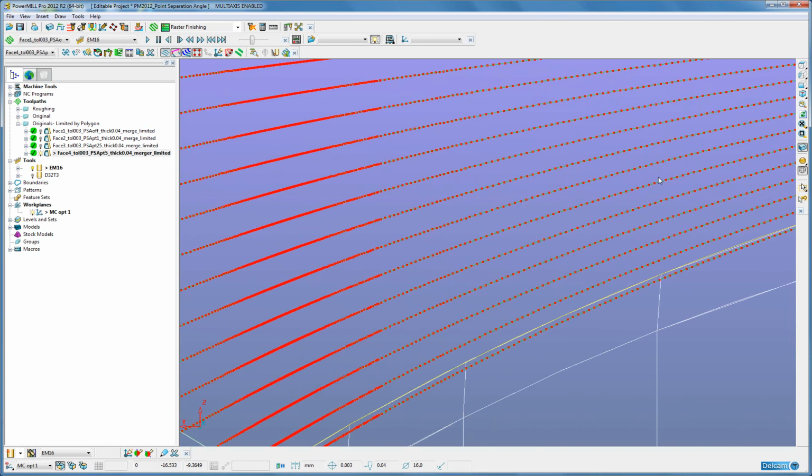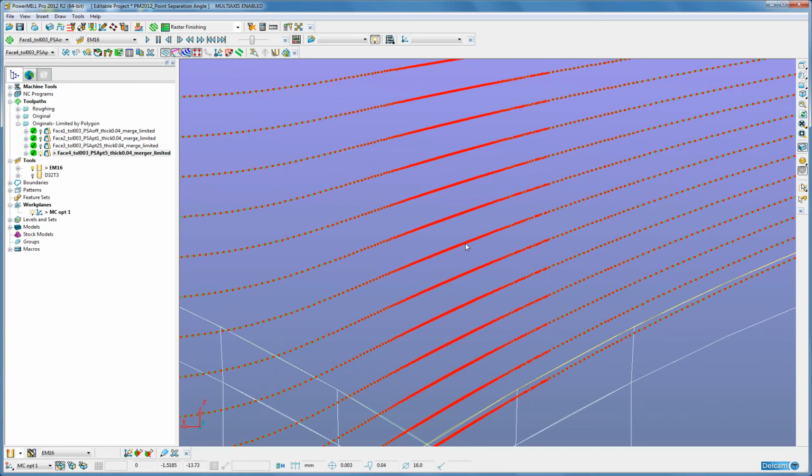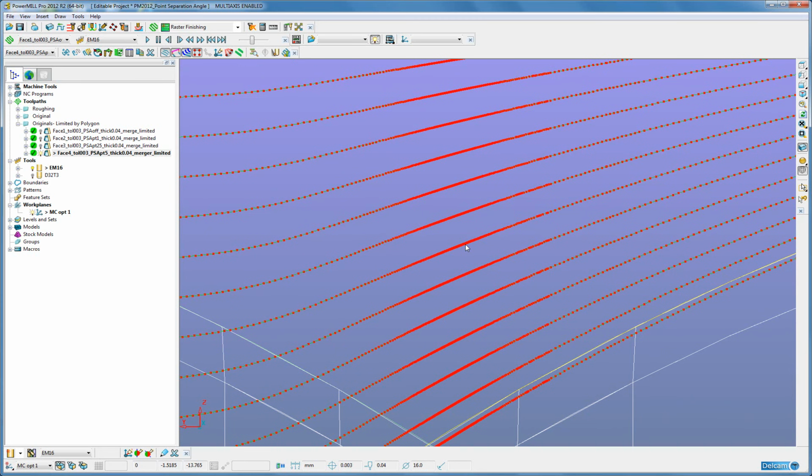while we have equal points around the nose flying part of the surface, when we get close to the vertical tool axis, where we saw the table spin around very quickly, more points have been inserted in the toolpath. In this instance here, the setting was set to 0.5 degrees.